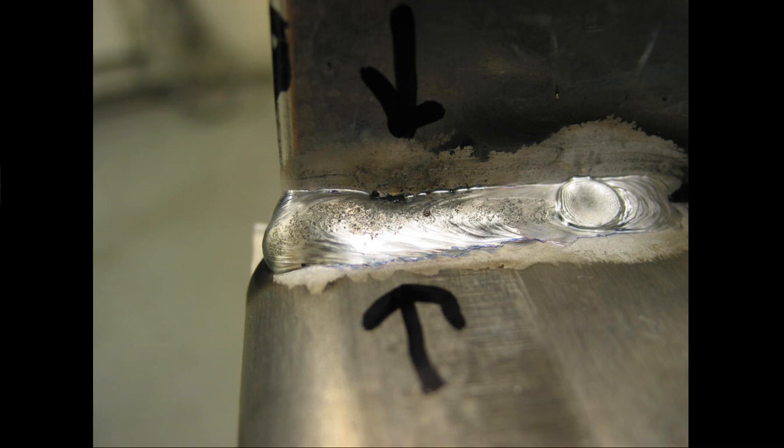And I do want to say this, if you're going to grind that weld out, take caution, because when I do practicals, using that die grinder is part of my criteria. Everybody should and needs to be able to practice with a die grinder to make sure that you never, ever, ever touch base metal. That die grinder should never touch base metal.